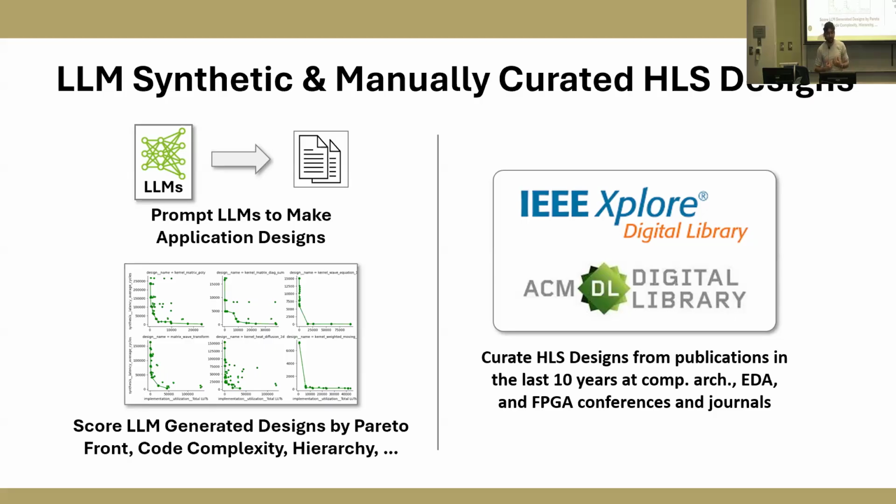One reason I might generate something as HLS is because HLS has better metaprogramming, so I can use template functions. If I generate the Verilog and need to make a change later, I might have to change the scheduling, the pipelining, all of this. I can't make a simple change. But if I generate the HLS and want to change something about the algorithm without changing too much about the architecture, I can do that. So this is one example.